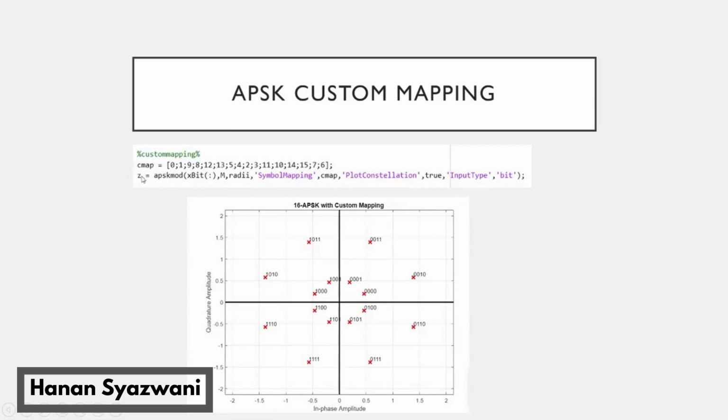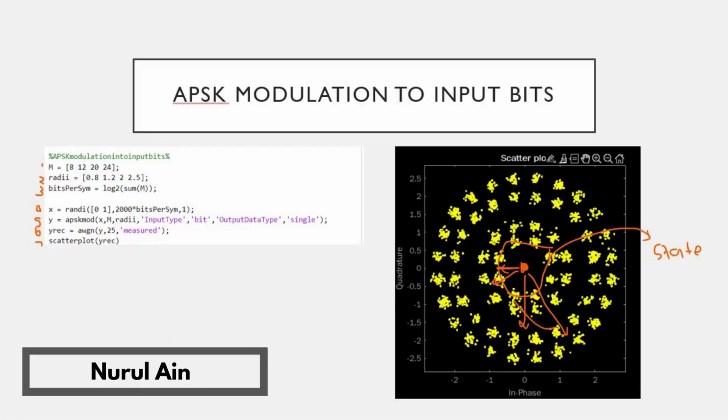Firstly, we create a custom symbol mapping vector here. Then, we apply APSK modulation with a custom symbol mapping. Then, we plot the constellation. Binary input is used to highlight that the custom mapping defines a different gray symbol mapping. APSK modulation to input bits.